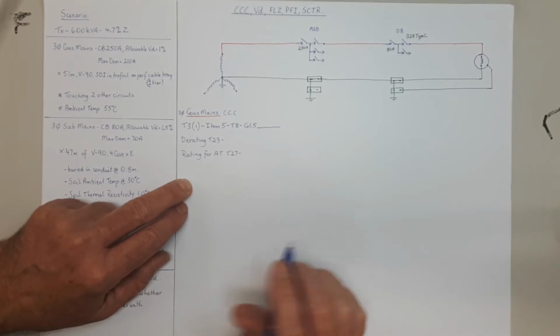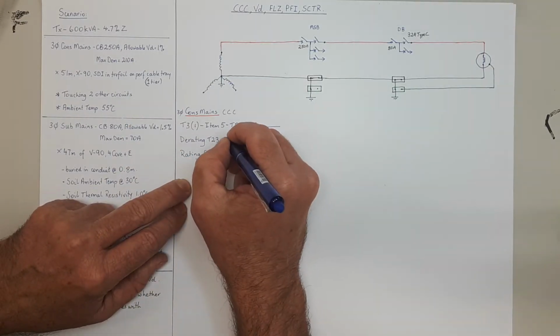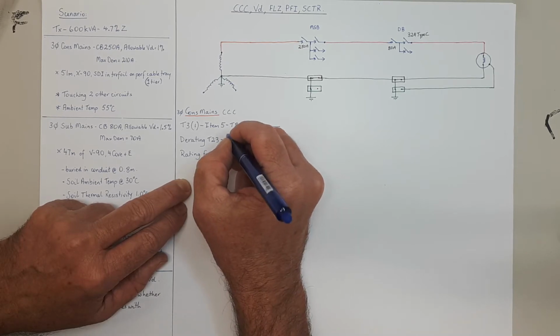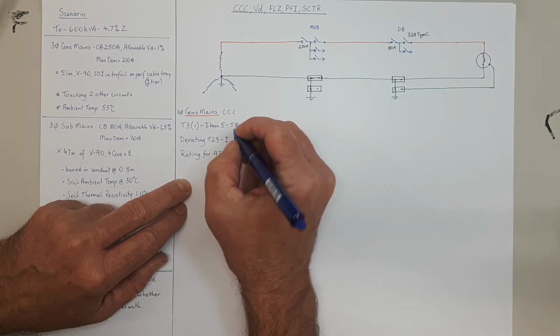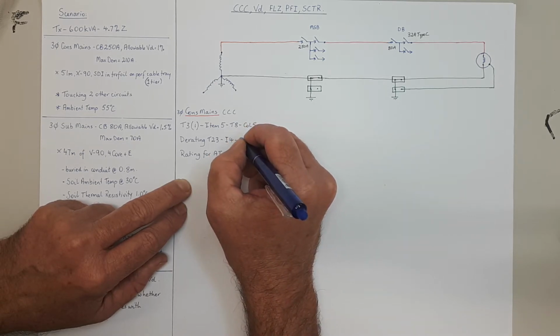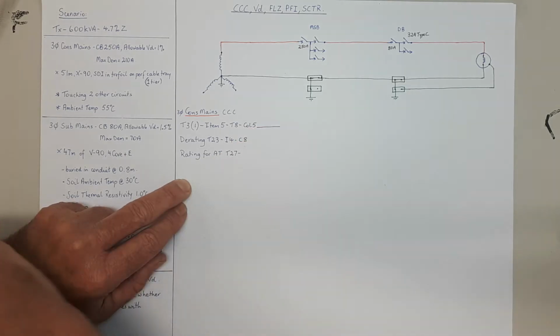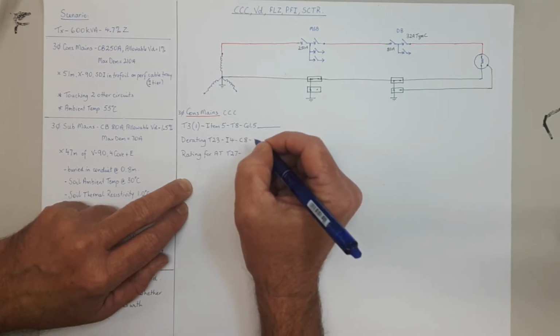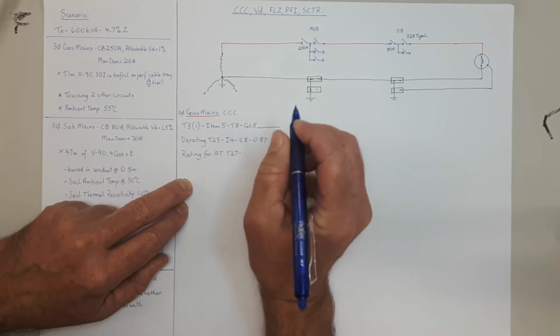So if you go to table 23, look for the trefoil configuration, and of course it's touching and not spaced, so that's a different item. We're looking at item 4, and we're looking at column 8. If you look at column 8, you'll see it's touching 2 other circuits, so 3 circuits in all, and it's going to be 0.87. That's our first one.